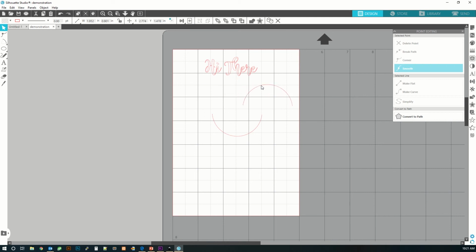When you select your erase tool and click the outline option, you can see the eraser will only erase the outline of your drawing. This can be helpful in some instances, but when we want to create a solid shape, we need to click the solid button. Here you can see Studio generates a solid shape from our erased design.